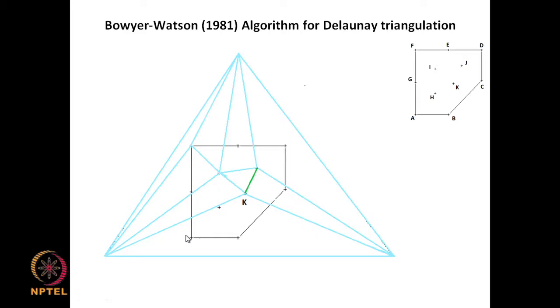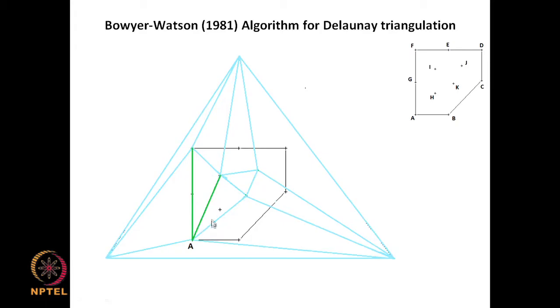we have created 2 new diagonals, and after applying the Delaunay's triangulation criterion, we are joining this and this and not to triangulate the points better. Then after doing this we look at the remaining quadrilaterals and make one more change here. The changes that are made are shown here in green color. At this point we are making change in this diagonal and in this diagonal. So, now you have a set of triangulation which is again the best possible thing in this way.